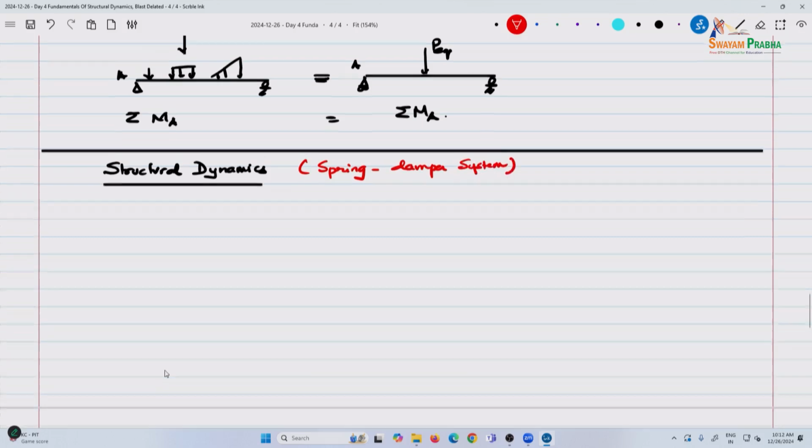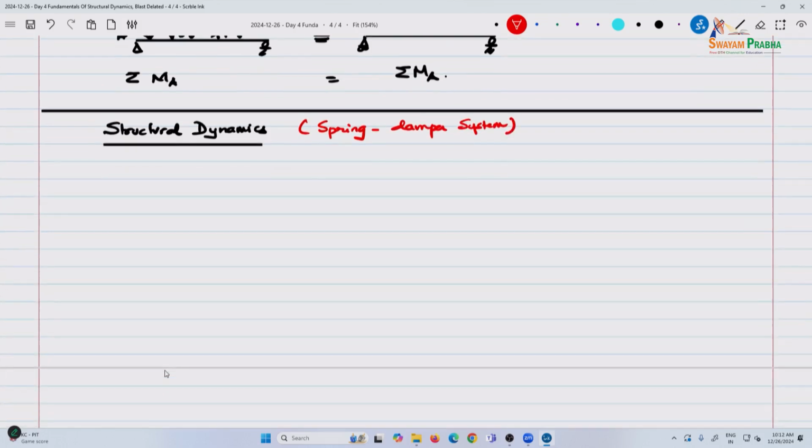I'll start with a damper also, although I mentioned that damping is not very effective in blast, but if you're developing a MATLAB code or any similar code, you have to include the damping and then set damping to a very small value. The program we will use also has damping built into it. In quasi-static loading, damping does play a role, and our analysis includes the range of quasi-static as well. So that's why we will incorporate that.